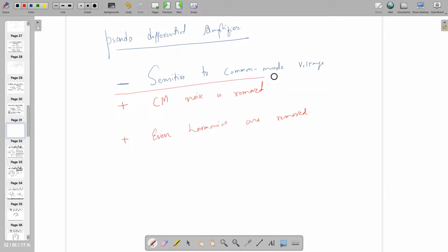So we are worried about this part, because the output is not having the proper swing, or distortions are observed. We don't like that. We want better and better signal to noise ratio. We want better total harmonic distortion. In different circuits, in power electronics machines, communication circuits, or data converters, you need to take care of such quantities so that you can achieve the required resolution or the required specifications from that particular circuit.